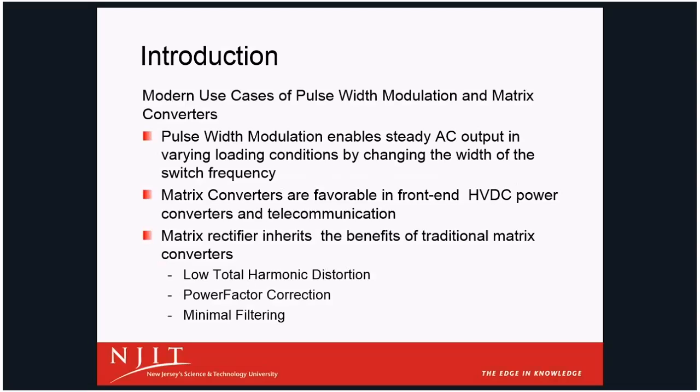In this presentation, they'll just be discussing the buck type, which they've denoted as a favorable source because it allows you to have high input line voltages without the high voltage ratings that you would need for its boost counterpart.